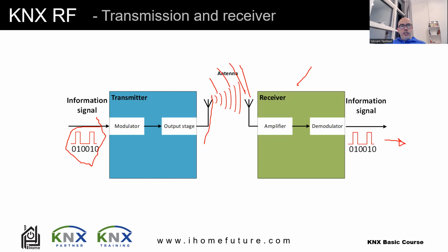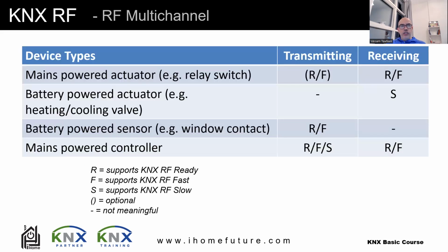One thing appeared when they were using the RF in general, that because RF can be used by other devices as well, then you might have some circumstances where there is jamming on one channel. So if you are using one channel, one frequency, and that's it, then maybe you have some kind of jamming or disruption from other systems in the area itself, maybe from other RF devices, something like that. This is why they came with something they called multi-channel, meaning that I have a central channel